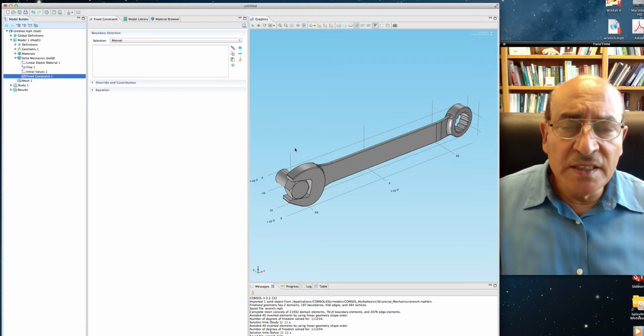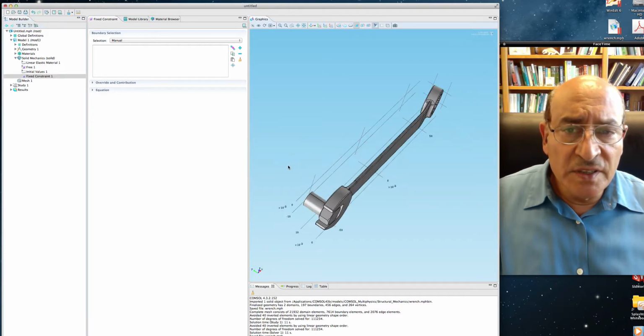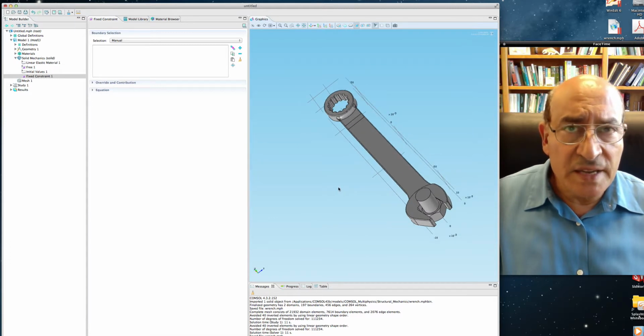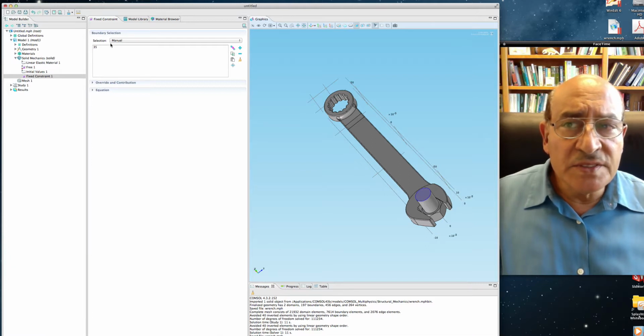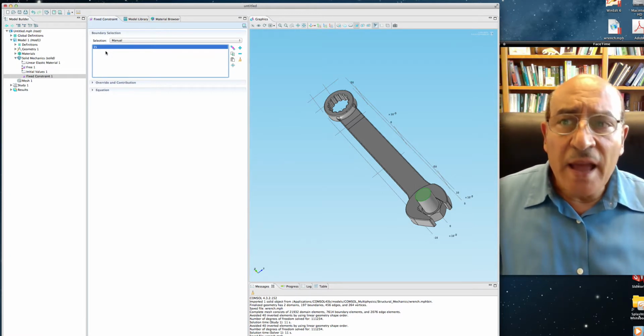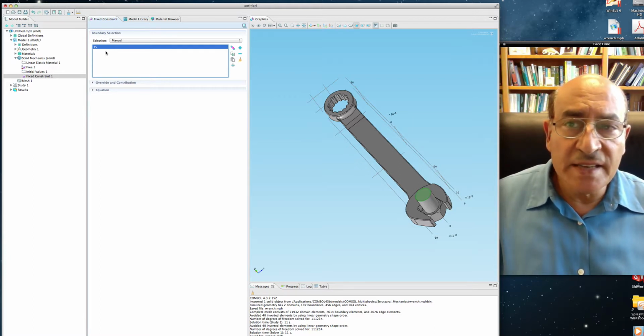And now we want to select manually the particular boundary. So I have to go to the window and select one of the boundaries. Selection is two steps. First you left click, then it shows you the boundary in red, and then you right click, then it shows you in blue, and it will select it. It will show in the Model Wizard panel as boundary number 35. So that's selected, and it's selected as fixed constraint.